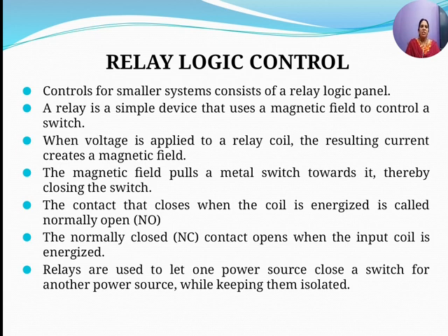In this context, I would like to tell you about relays. Relays are electromechanical switches that have a coil, and two types of contacts: NO stands for normally open and NC stands for normally closed. When the NO contact is on, the relay will pass the current to the load.